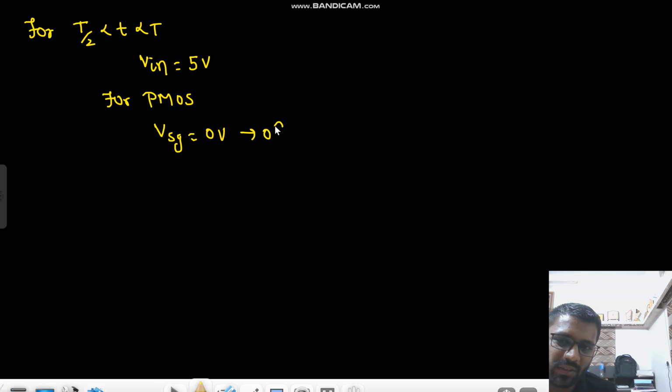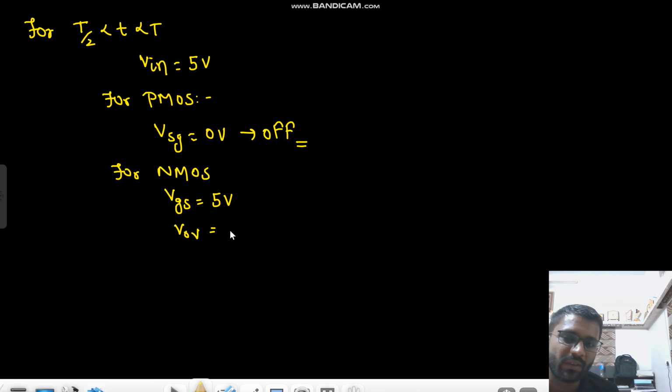That means it is off, right? So PMOS is off. And for NMOS, what is your VGS? That would be 5 volt. What is your V overdrive? V overdrive is 4 volts.